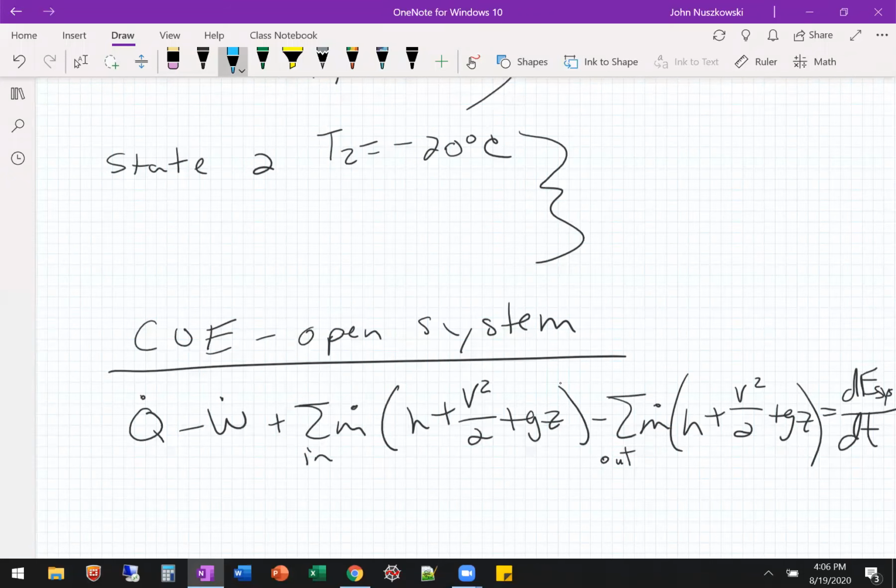All right, so we have this. Let's simplify this. It says enthalpy, and that is what we're going to end up with. But what can we cancel here? I'll cancel what we've already said. Adiabatic, so there's no heat transfer. It's steady state, so we've used that one. An easy one: there's no change in potential energy.